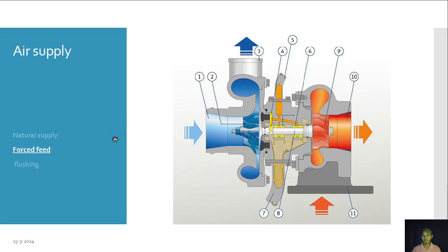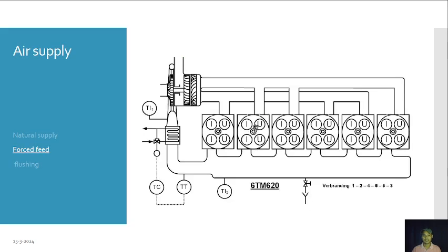On the compressor side, fresh air from the engine room will be drawn in, and then it goes to a charger cooler, then to the scavenge space, and to the combustion chamber inside the engine. After it enters the combustion space, the piston will compress that air, and then injection of fuel occurs, and then combustion occurs, and the exhaust of that combustion will go into the turbine. That's how the turbocharger works. Okay, next.